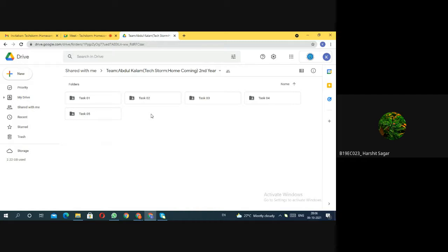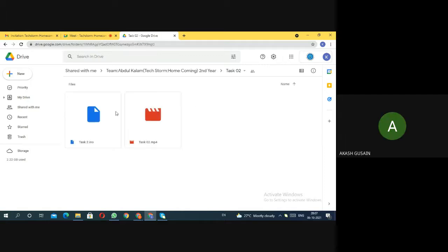No, you have done this part in your basic electronics, right? In first or second year. Yes, sir. LED is also a diode. So what will happen if you connect a diode in reverse bias? Will it work? It won't work, sir, because the separation between the P and N junction of the diode will become more, sir. Okay. Go to the second task.